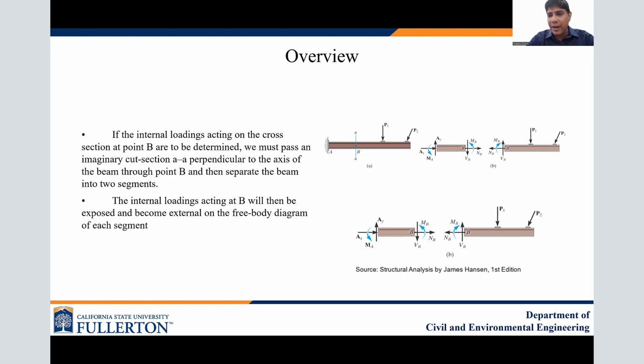Either you can cut from the right or from the left, but overall it maintains the equilibrium situation. So if the axial force is moving forward on one side, on the other side it will be going back. Whereas shear force from the right side is downward, from the left side is upward, and bending moment is counterclockwise from the right side and clockwise from the left side.